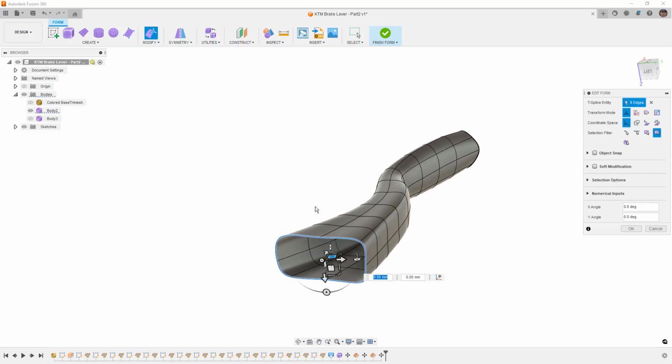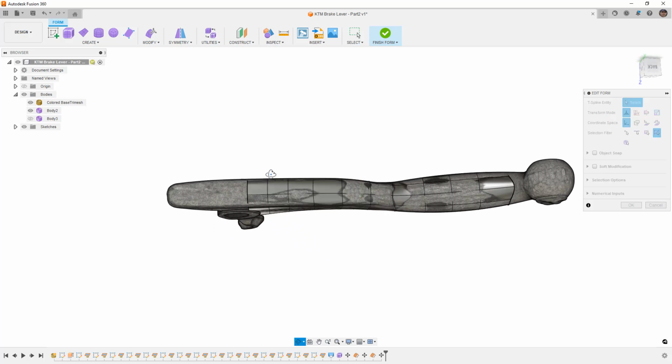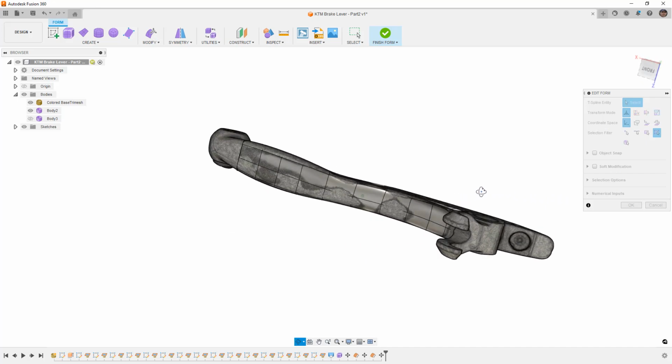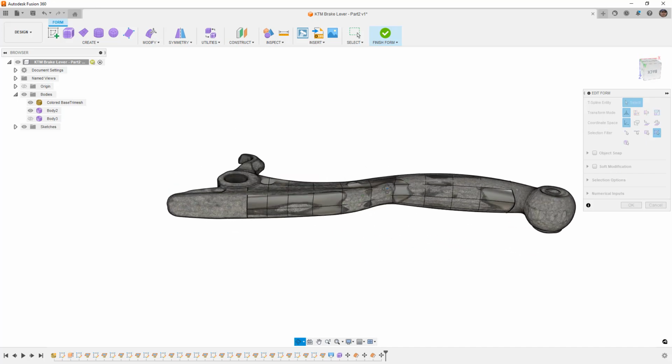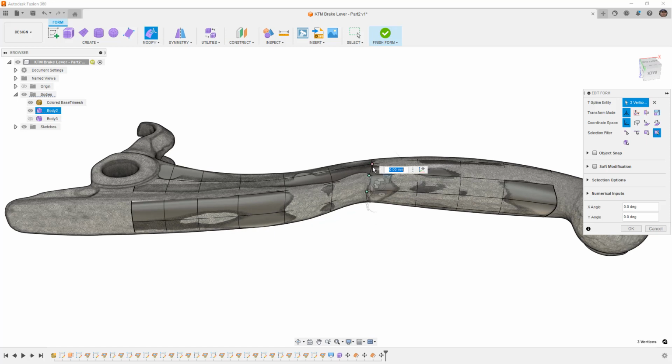And at some point we can use pull and pull it down. We're never going to be able to use these freeform tools to get all of these little details. It's just not what it's used for. So at some point, you're still going to have to make some prismatic parts. But if your end goal is to try to replicate this shape and do it quickly with as smooth as possible geometry, freeforms definitely, in my book, will beat using those mesh section sketches because we are pulling down to the mesh, but we're pulling down at each of these individual points, which means that we're spreading that out over, and the difference between each of those, the geometry is much smoother.